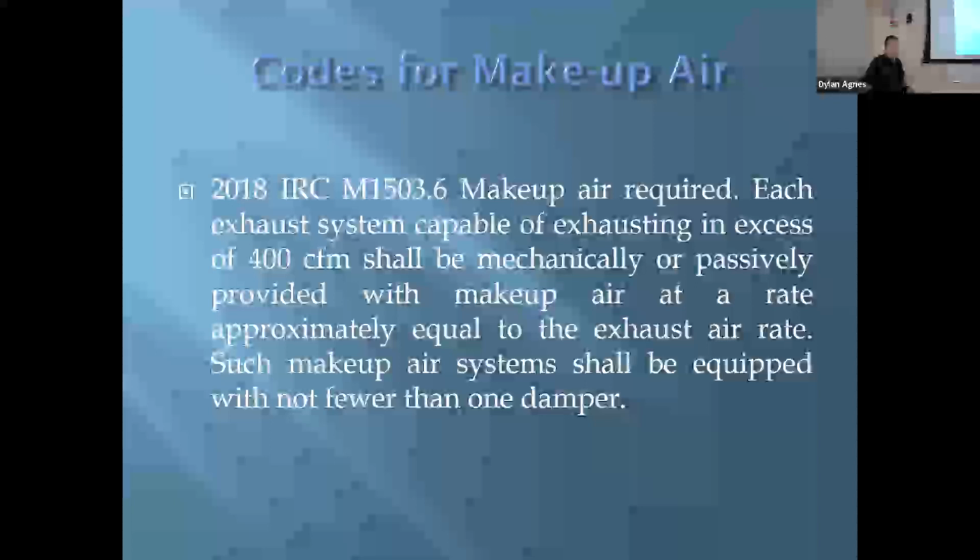And if you're not using a compensating type hood, which are very expensive, we're talking about massive holes in the walls. And I'll show you a way to calculate that makeup air. We're talking really big holes. And so when they put in the makeup air that it calls for, these areas are super uncomfortable because they don't have a way to condition the incoming air. And so if you're running this thing in the wintertime, it can be harsh, to put it mildly.